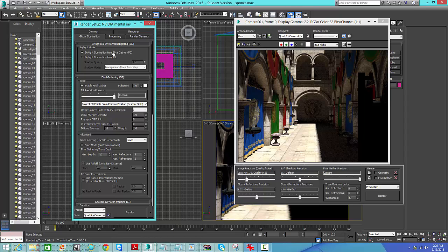But unless you're doing photoreal rendering for visual effects, or trying to match a photo plate, the skylight illumination from IBL might be more beneficial because you'll have more control of things afterwards. As far as doing it for this stuff, having it in the final gather will make the render a little bit faster. The other calculates things differently, so it will take longer to render.